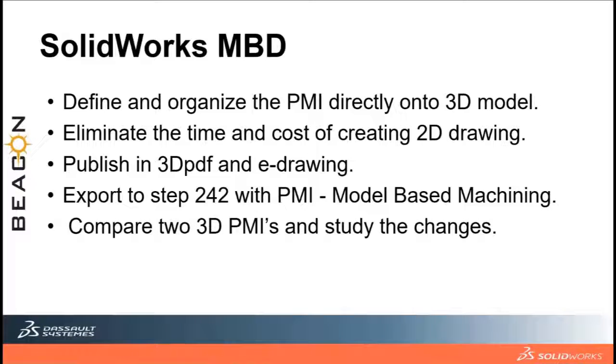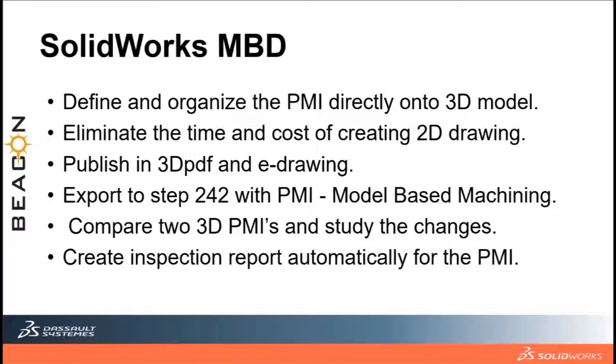And we can compare two 3D PMIs and study the changes. Basically, when we have revisions or different versions of two components, we can directly compare the 3D PMI in SolidWorks MBD, and we can check what the modified changes are, what changes have been added onto the model. And as we saw, we can directly create an inspection report automatically for the entire PMI within no time. So this will save a lot of time and a lot of effort for the users and the engineers working on the models day to day.